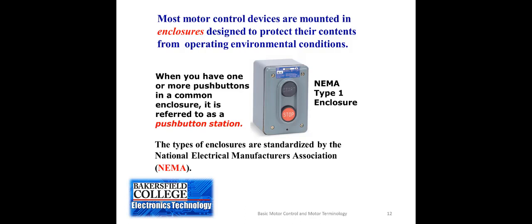Now when you attach a push button device or any kind of switch or control, we have to put it in some type of an enclosure. Sometimes it's a control panel that inside has other components. It could have relays and contactors and other devices that are inside. It could have time delay relays or whatever. Or we might have, like this, a start-stop push button station, an operator control station where the two push buttons are mounted in their own enclosure.